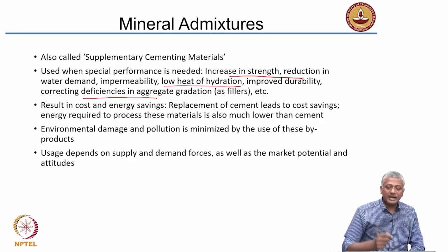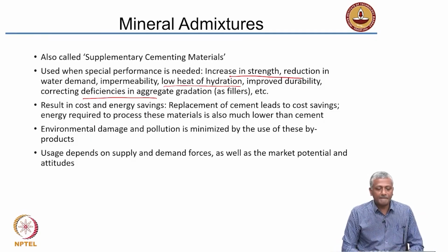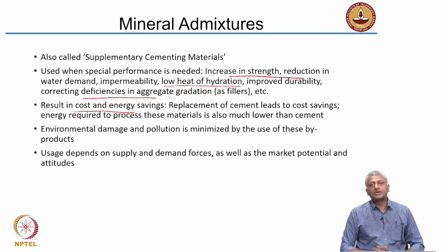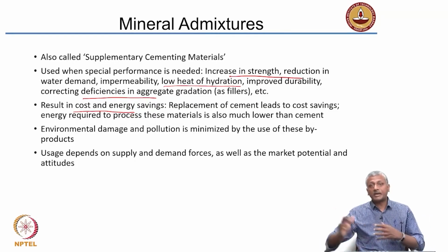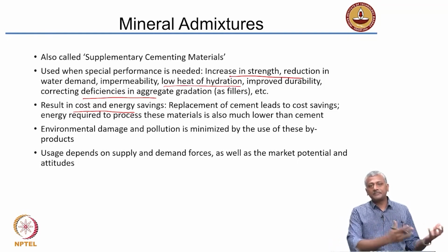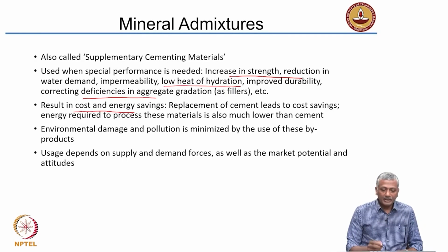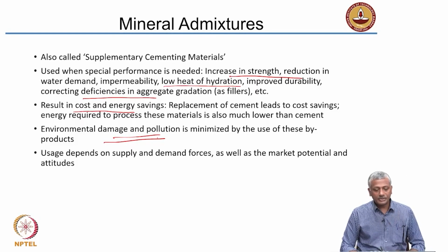Sometimes you may also add these materials as fillers, and they can help improve the overall gradation of your material to get good quality packing inside. Most importantly, they will lead to cost and energy savings, because you are replacing cement, which is the most costly ingredient, with the supplementary material, which is a byproduct or a waste from another industry. So, environmentally friendly, at the same time you are reducing the cost and the overall net energy consumed to make the concrete. As I said, byproducts are being used, so environmental damage and pollution is getting reduced.